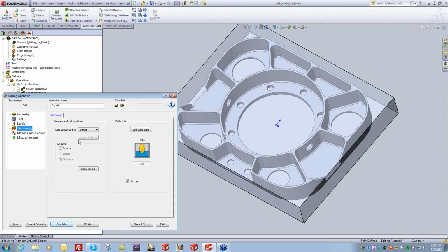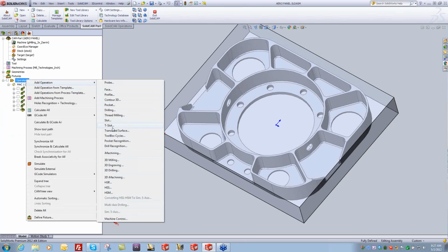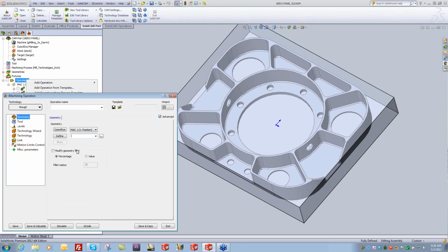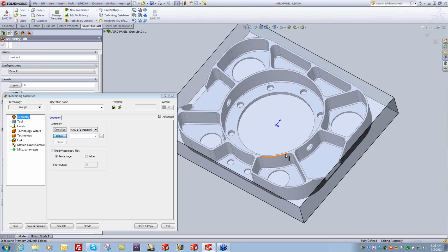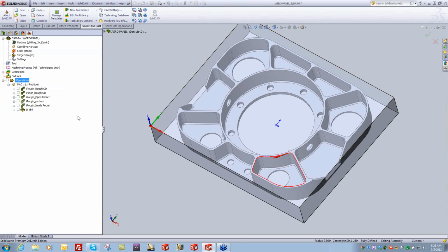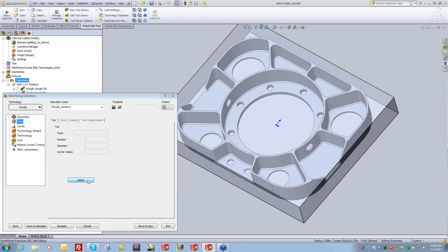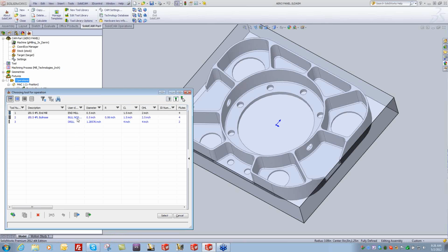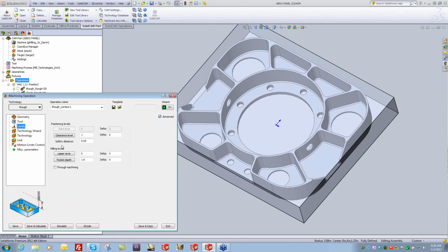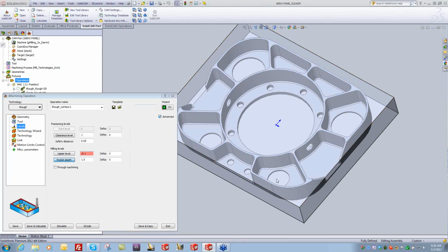Now that we have a drill sequence in there, if we go to iMachining and we want to use a previously drilled hole instead of a helix, we're still going to define our pocket. So we'll define it over here, just like we've done with all the rest. Grab the same tool, levels again, upper level, pocket depth.